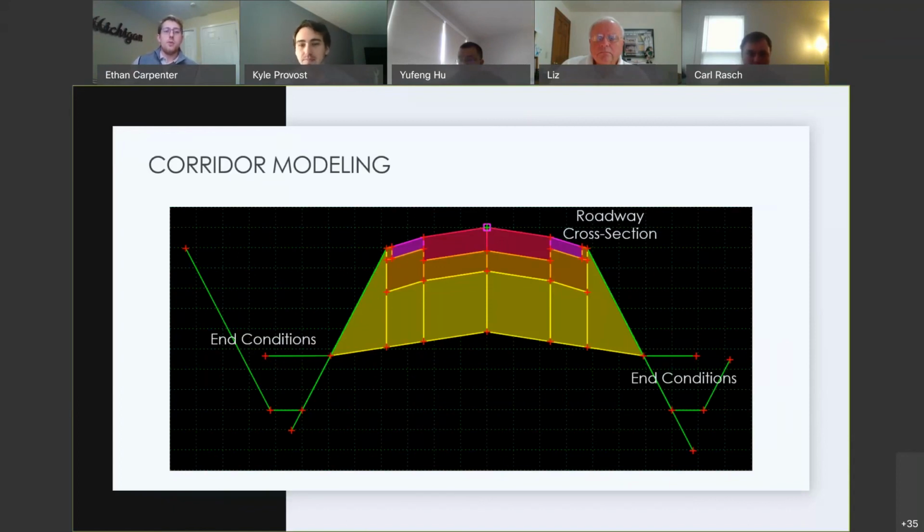We allowed our template to solve for 3 separate conditions with the following priority within the corridor. First was a bottom trapezoidal open ditch. Second, a flat roadside condition. And lastly, it was a 1-on-4 slope, which would extend infinitely until it intersected with the existing ground elevation.